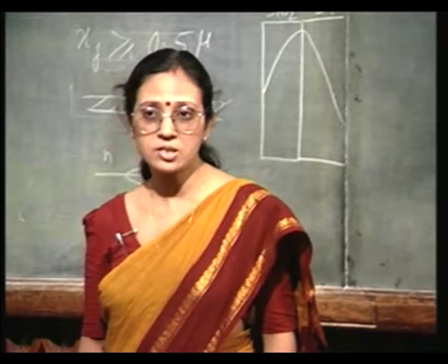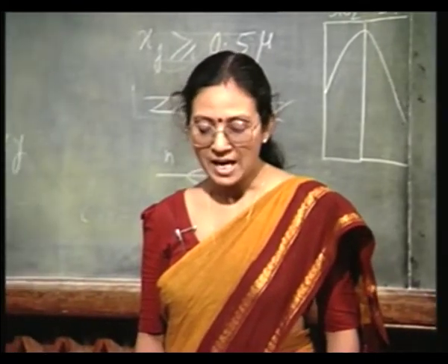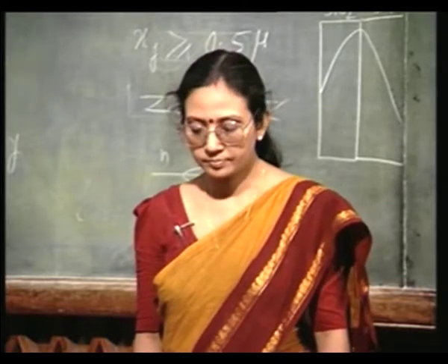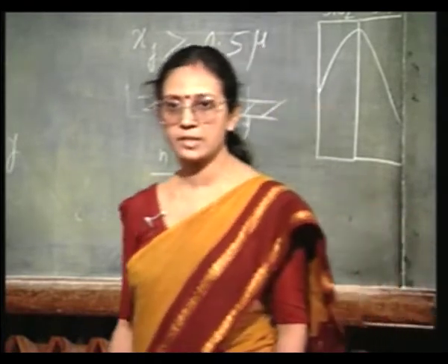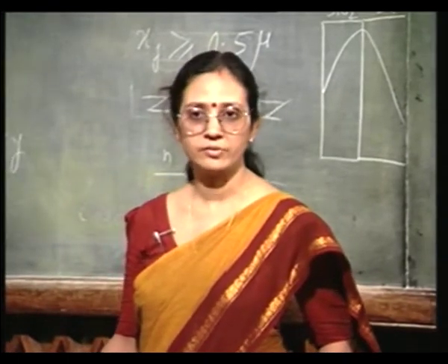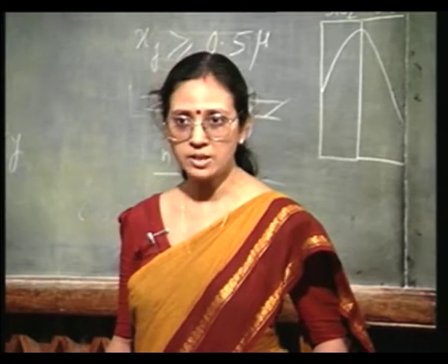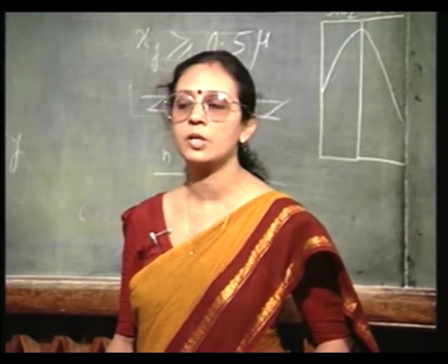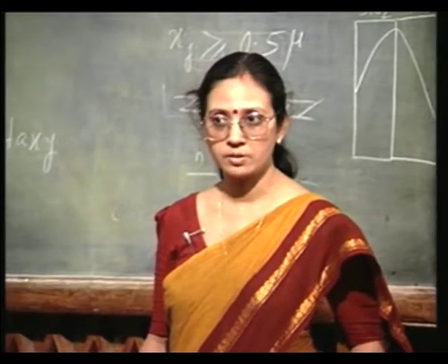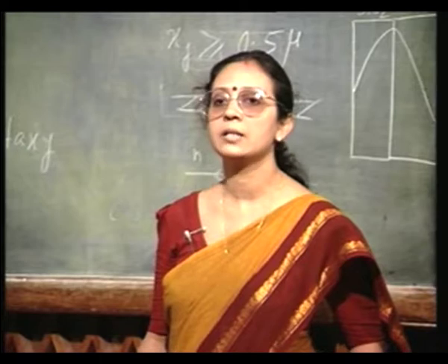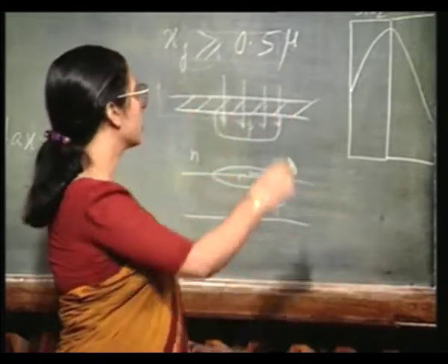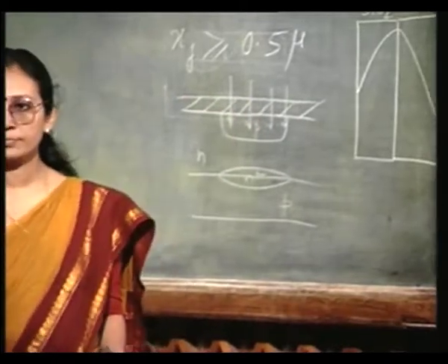If there are dislocations, beta is going to be down, there will be an increase in the leakage current, and breakdown voltage will come down, all kinds of undesirable effects. So, you must ensure that after the implantation, the annealing is not done in an oxidizing ambient, and in order to keep the annealing time and temperature at a minimum, you should have the implantation done through an oxide layer.